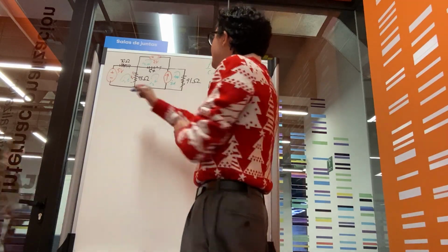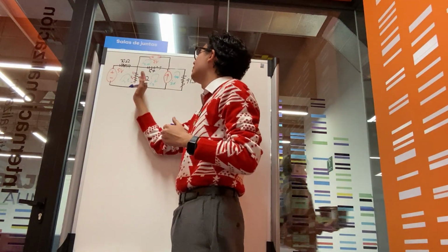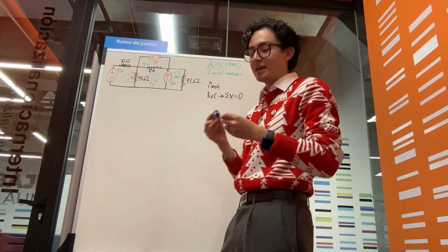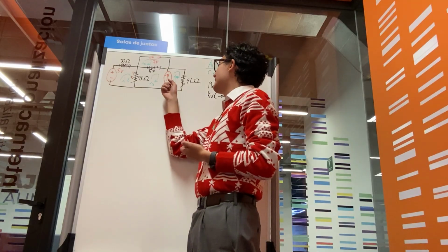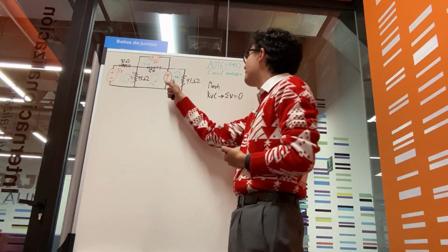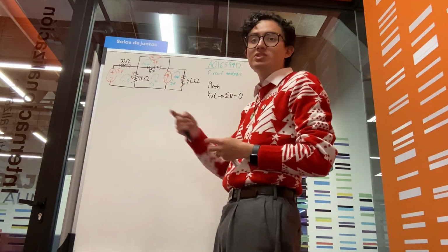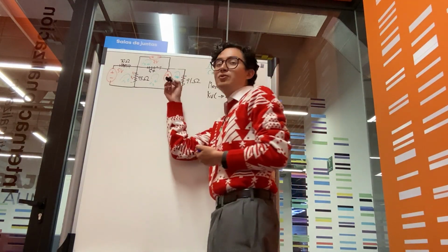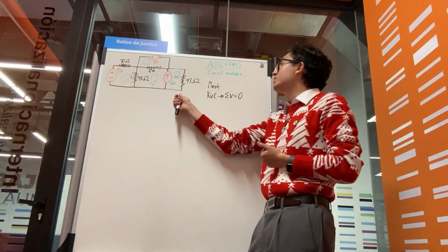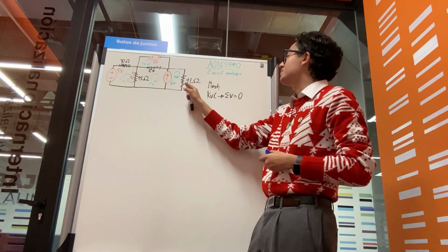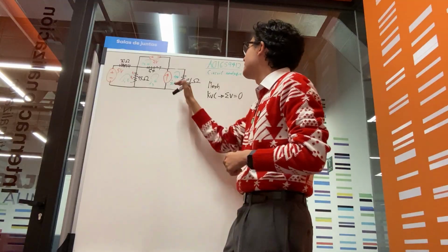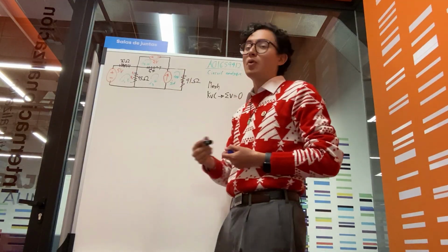Now in this case, we have to get the voltage passing through this resistance, which we're going to call Vx, and the power given by the current source. It's very important to notice that we cannot apply Kirchhoff's voltage law directly to the current source, because its voltage is unknown. Therefore, we first have to calculate the voltage going through this resistance of 41 ohms, and since they are in a parallel configuration, the voltage here will be the same for both.